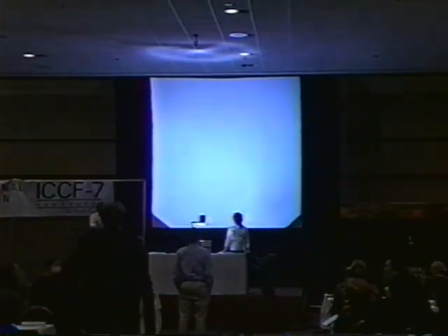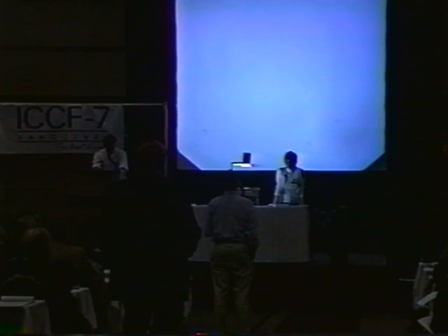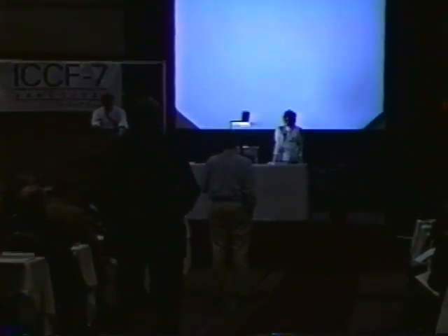Professor Huggins: I think this is very nice work, but it's very difficult to separate the kinetic effects of the presence of grain boundaries from the final composition effects. I agree with you that hydrogen, it's well known, diffuses faster down the grain boundaries than through the bulk. But what you measure for loading is not the rate of transport of hydrogen into the material, it's the final amount of hydrogen. And that will only depend upon the grain size if you also have hydrogen located